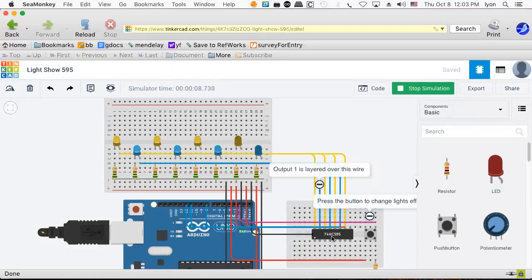Because a shift register like that uses the serial clock and the serial data in, from master out, slave in, which is MOSI. Using the MOSI and the SCLK line, you should be able to strobe data in and have it display on your screen like this, or perhaps go to your little DAC.